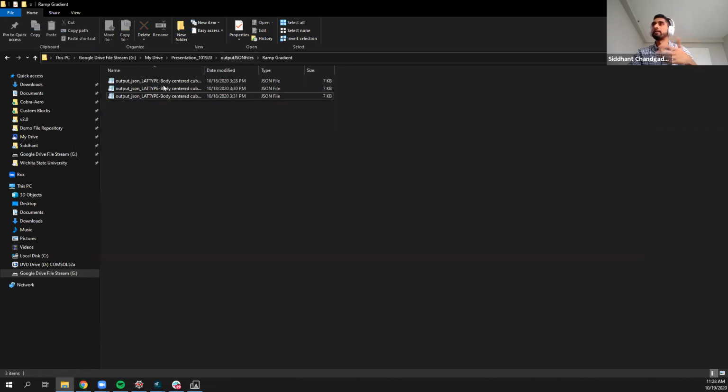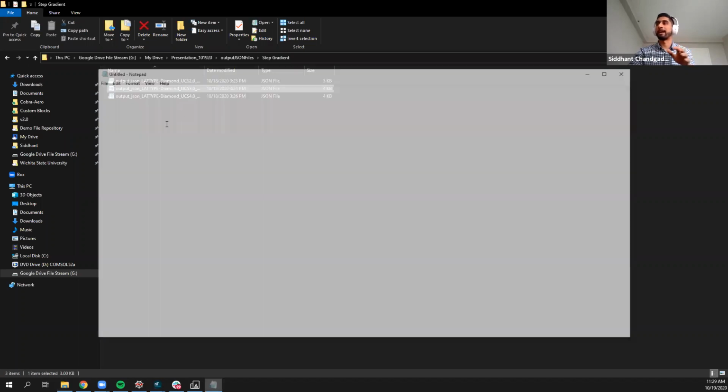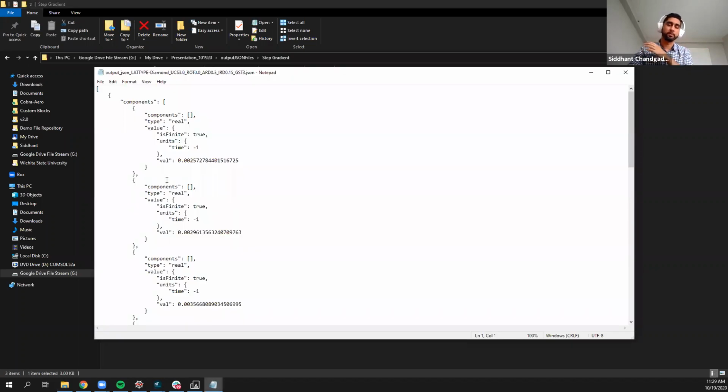So this will run, and we can do it for the step-based gradient. And as I said, it just really improves the efficiency since I can just run this passively and my computer will just churn out all the different meshes and all the different lattice cell types and their associated eigenfrequencies when it runs the modal analysis through nTop CL.